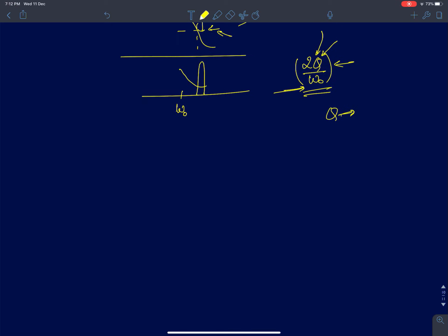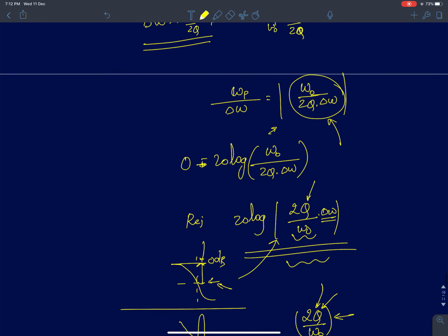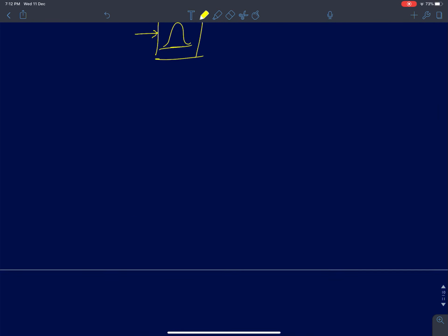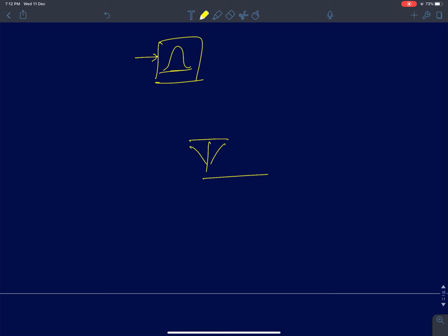One very simple way to solve this problem is what we call the heterodyne architecture. First we introduce a bandpass filter with a certain Q. Understand this: eventually we need to suppress the interference as the signal progresses through the RF chain. So let me just redraw the receive chain again. From your antenna you will have a bandpass filter, just to filter out the interferers. Then the LNA, which is going to see large interferers, so you have to filter them out. After that the mixer is going to see some interferers, which also needs some filtering.